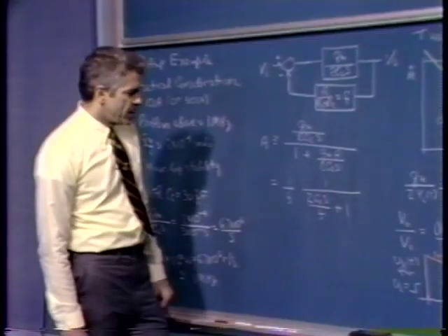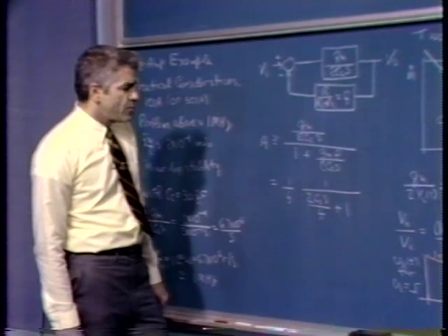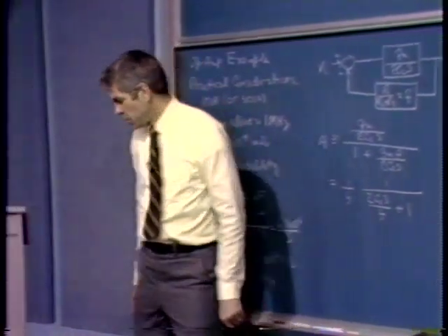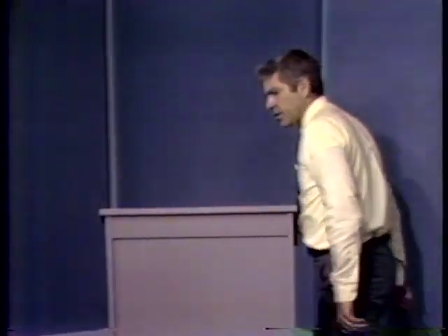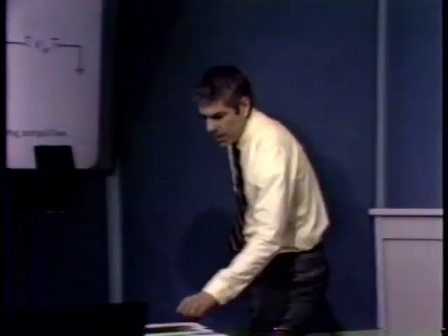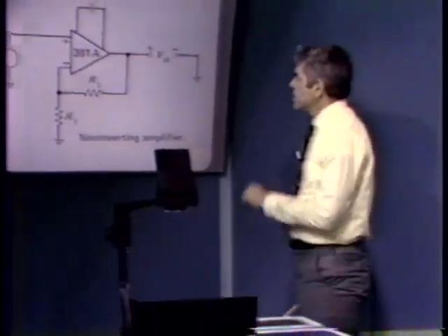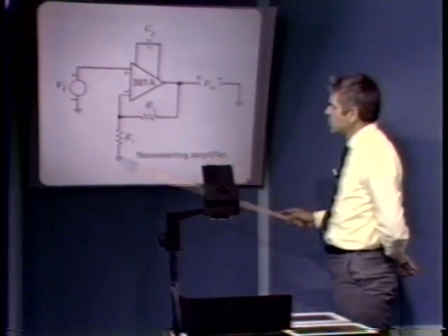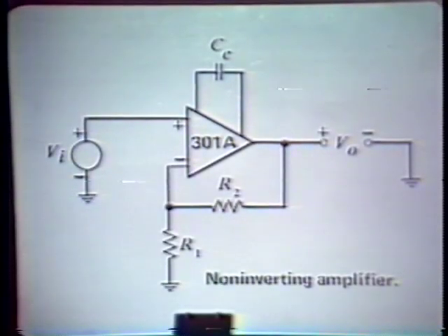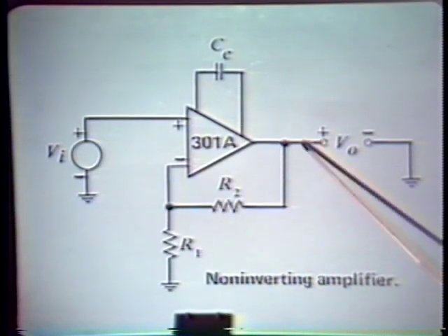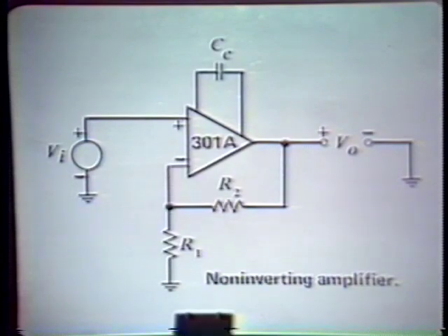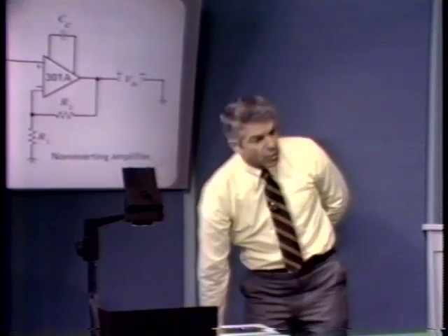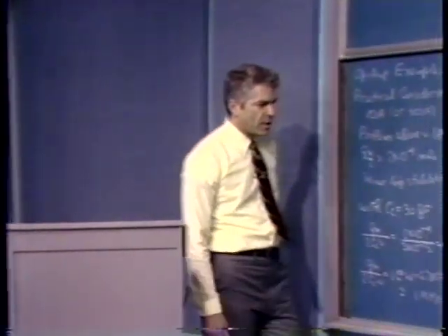Now, the problem is that as we go to larger and larger closed loop gains, in other words, if we go back to our original amplifier, in order to get higher closed loop gains, of course, we'd make R1 smaller relative to R2, thereby lowering F. And since the ideal closed loop gain for this non-inverting configuration is, of course, simply 1 over F, as we lower that ratio, we make F smaller, we get progressively higher closed loop gains.